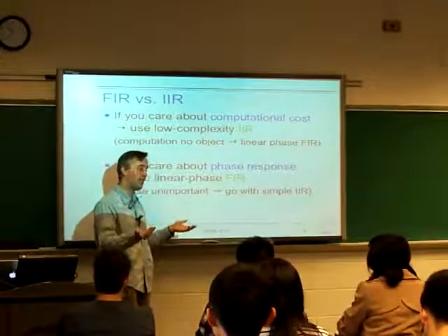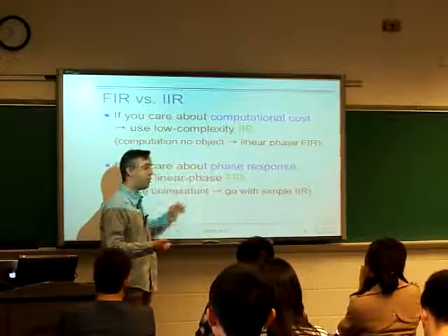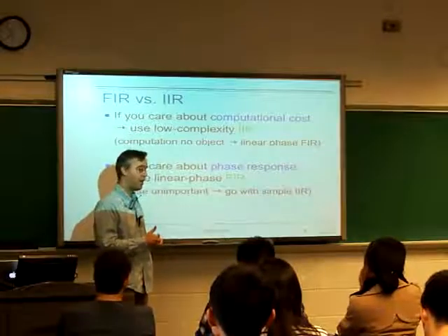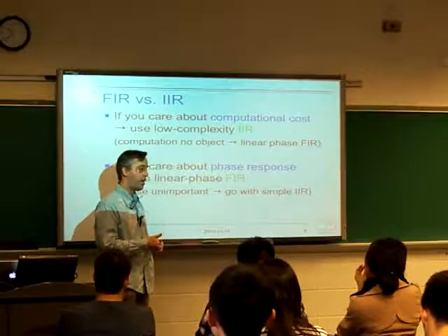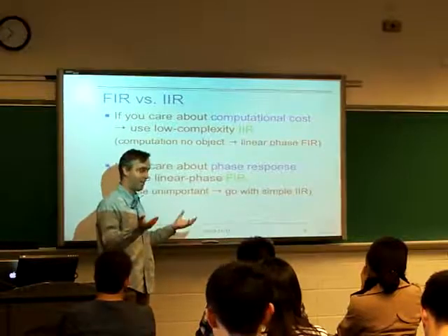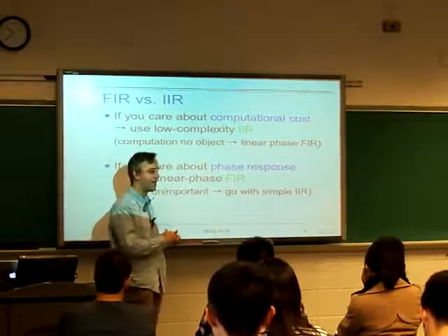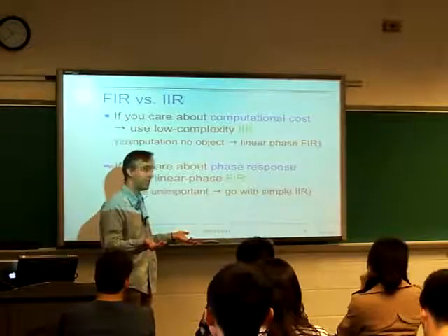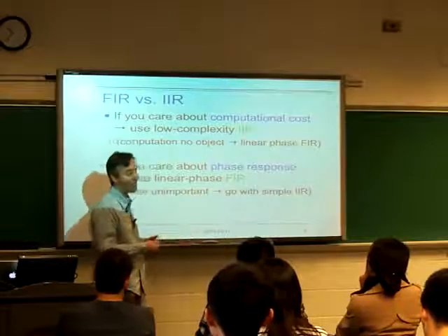So then it's like, okay, there was some phase distortion, but we could have gone with a 10 times or 50 times higher order filter done in FIR. We would have gotten rid of the phase distortion, but in terms of the application, if it's like tone control on some stereo, no one's going to notice, and so it's an engineering choice. It's like, what does it matter?